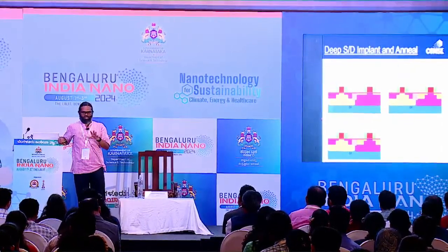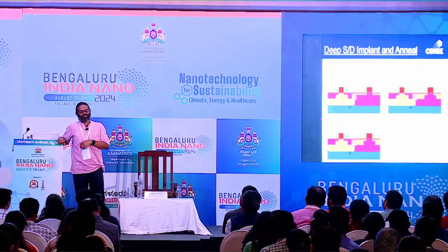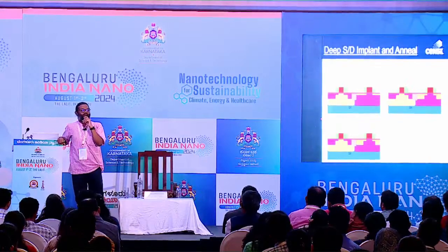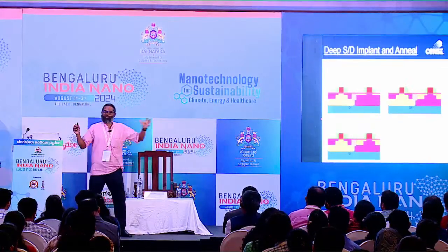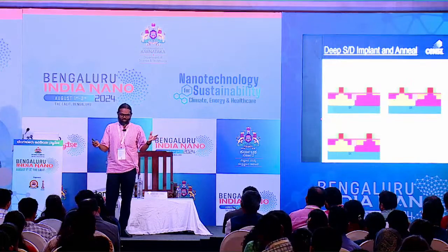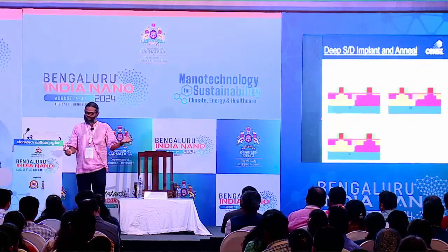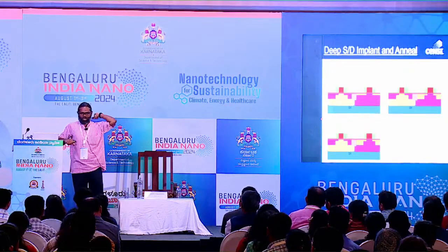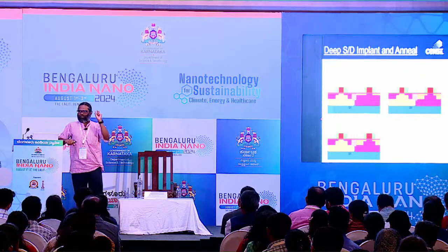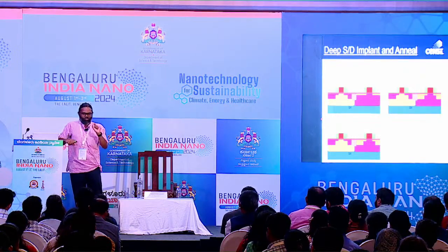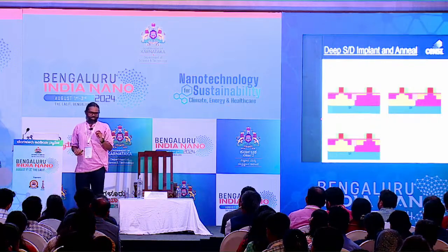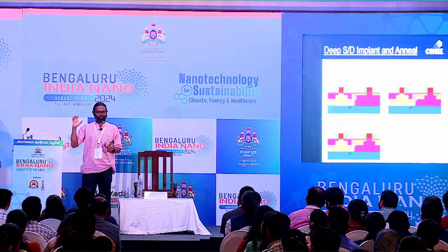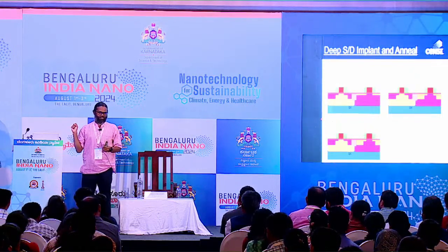So imagine 1050 degrees, let's say 1000 degrees, 1050 is the very accurate number. 1000 degrees, 1.5 seconds. How are we doing this? It's not a furnace. If you want to bake something, even to achieve 180 degrees, you have to wait about 10-15 minutes to reach that temperature. Imagine that you have to reach 1000 degrees in 1.5 seconds. How do we do that? It's not your regular heating coil, okay? This is done by using light. Infrared light, very high power infrared light that just flashes, okay?